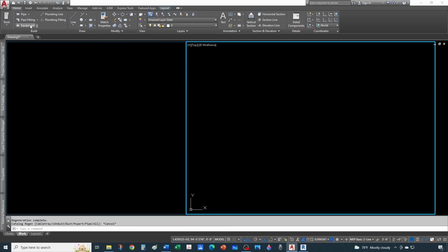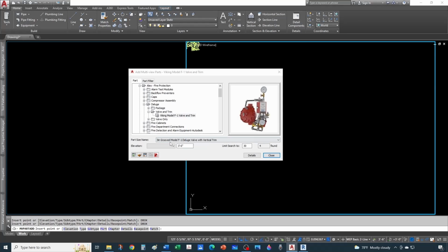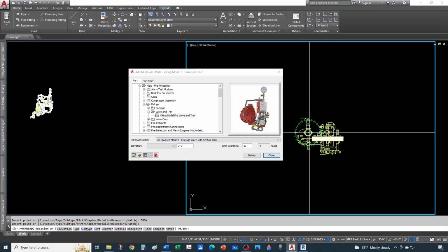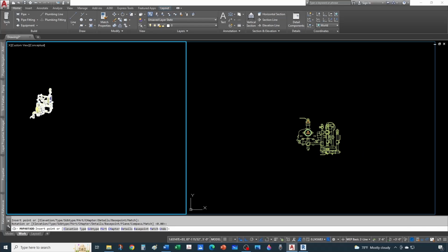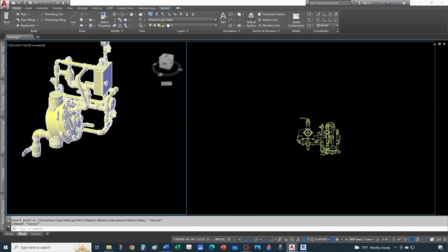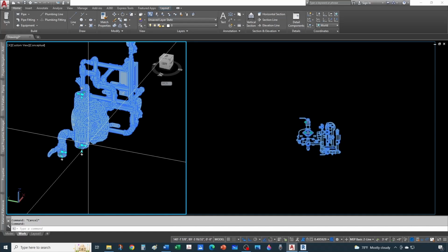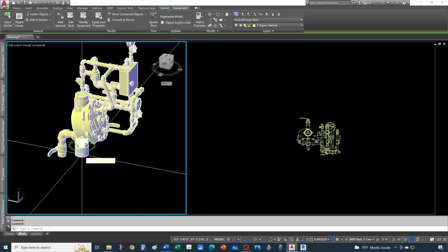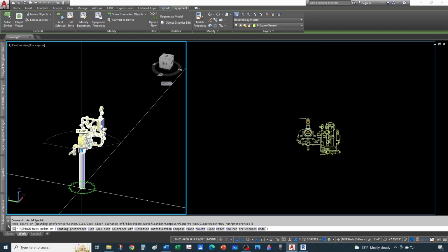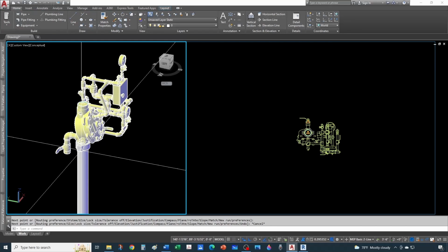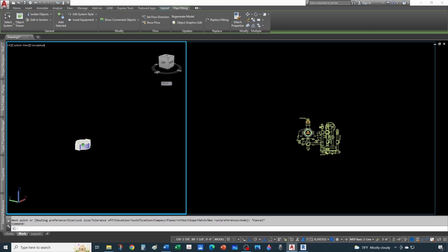We go to equipment and let's drop in our project a 4-inch grooved. Actually, let's do a 3-inch. Right? So let's test our in connector first. There you go. See how it provides the grooved coupling there.